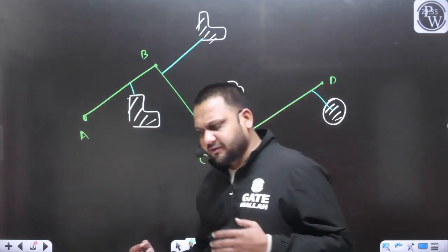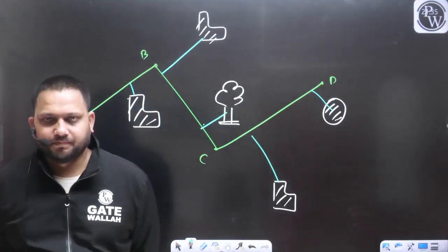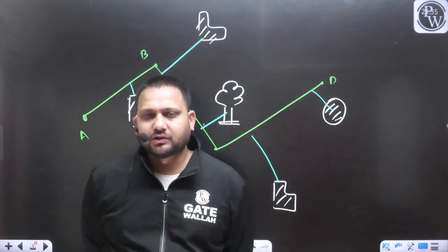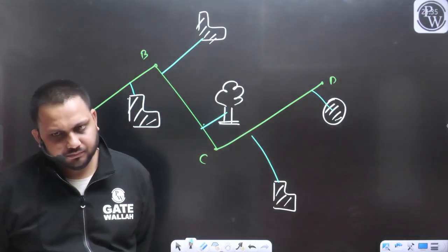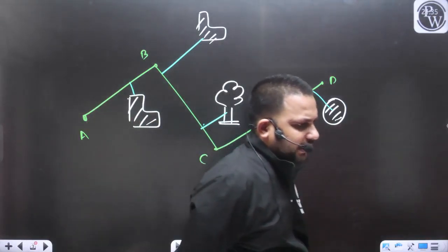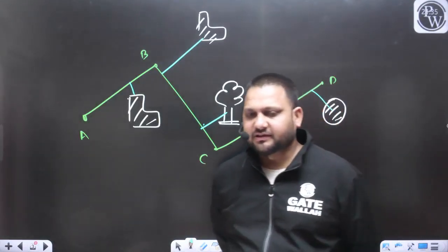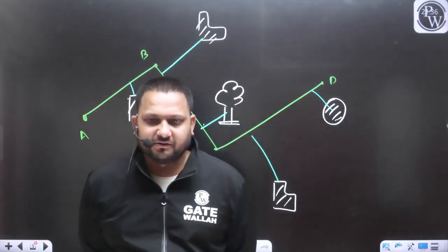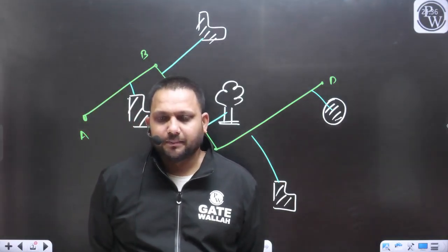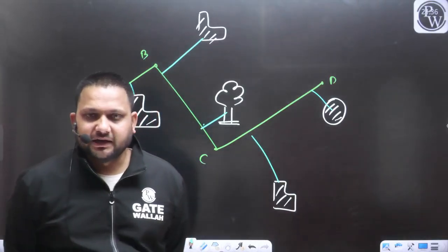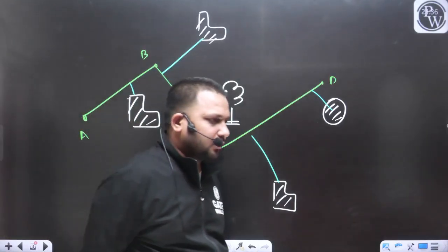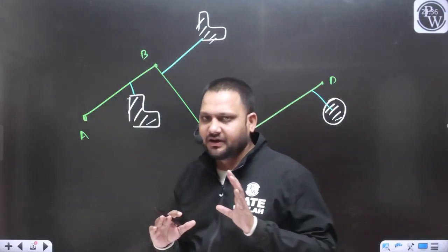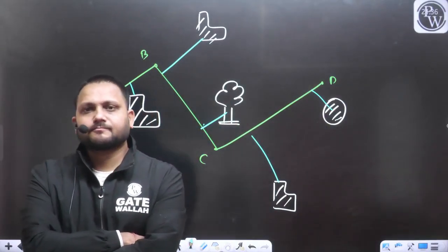It will totally depend upon the suitability. You can go for triangulation, you can go for traversing, any method, you can go for trigonometrical surveying. This is the example so that you can relate how we collect the data with the help of traversing. The point is clear? That information you can also collect with the help of the plane table survey, as we have already discussed in the case of traverse survey.